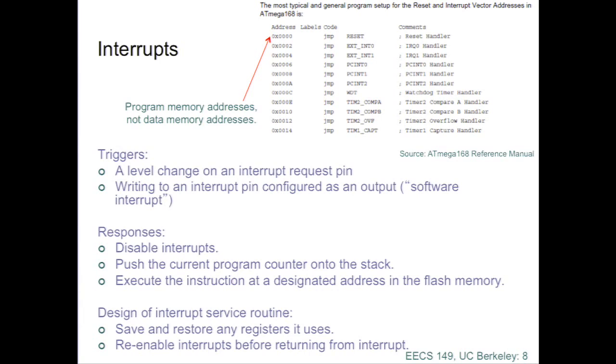Right. And then it's going to move on to the ISR, which is then going to push all the registers onto the stack. Right. And then by returning, it pops out all the registers into the PC, and it's done. Exactly. Yeah, you got it. That's exactly the dance that happens.